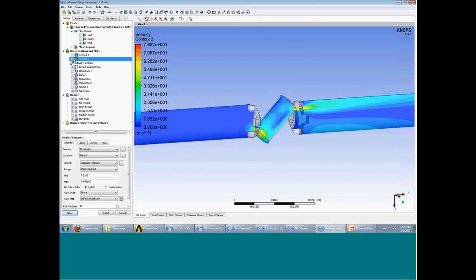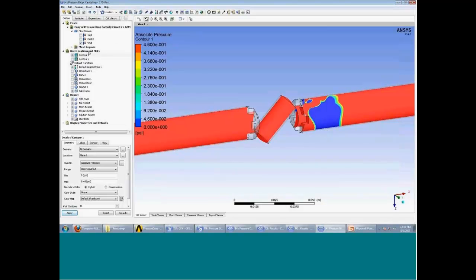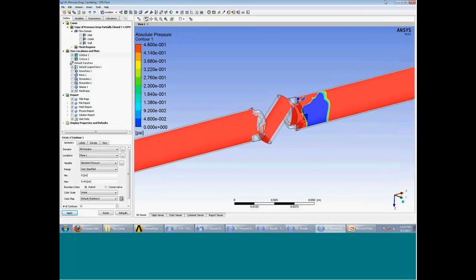In this case, what will happen is that the water will cavitate. So you can see, in this hypothetical scenario, that the pressure is well below the saturation pressure, causing the water to cavitate. And here, you can no longer consider water as a single-phase fluid. You have to make sure that you have the cavitation model included in your calculations, and that will give you the correct physics.